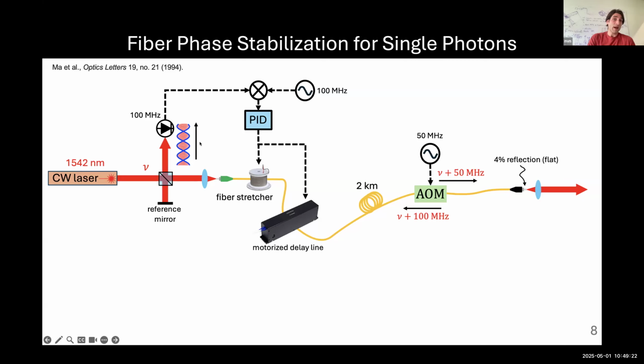What you were asking, Mike, was why are we not sensitive to amplitude noise? What we're doing is introducing an extra frequency to the light that goes through the fiber. Somewhere along the line we need an AOM, and this shifts the frequency, actually twice, because we double pass this fiber with the light.